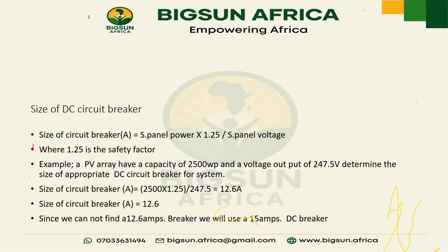But why will a client convince you otherwise, for what you know is a technical blunder, because you want to collect the money? Yes, you probably need the money, but do the right thing. If the client still wants to use his old tubular or dry cell batteries and is getting a new lithium battery, ask him to buy 2 inverters, so he can be switching between one inverter and the next, not switching between 2 batteries on one inverter. It's very, very dangerous.